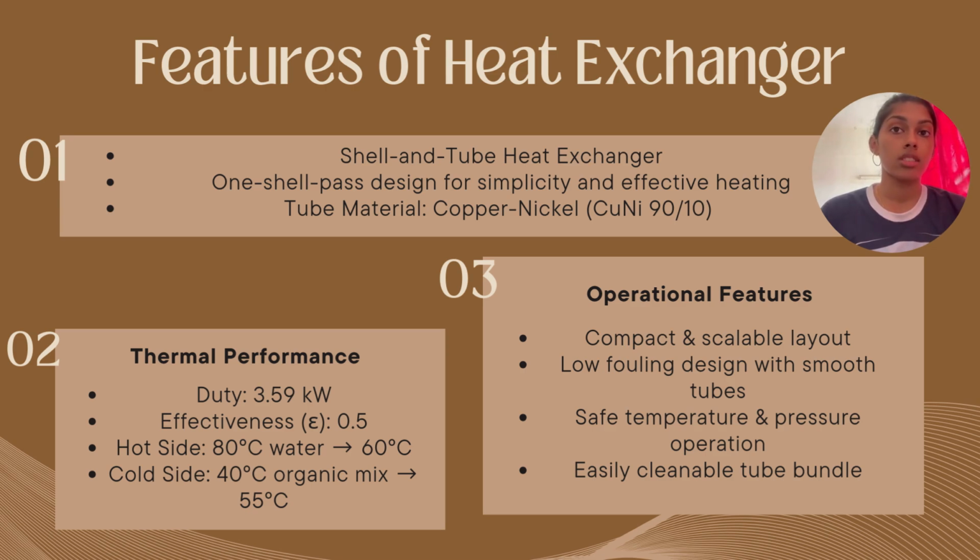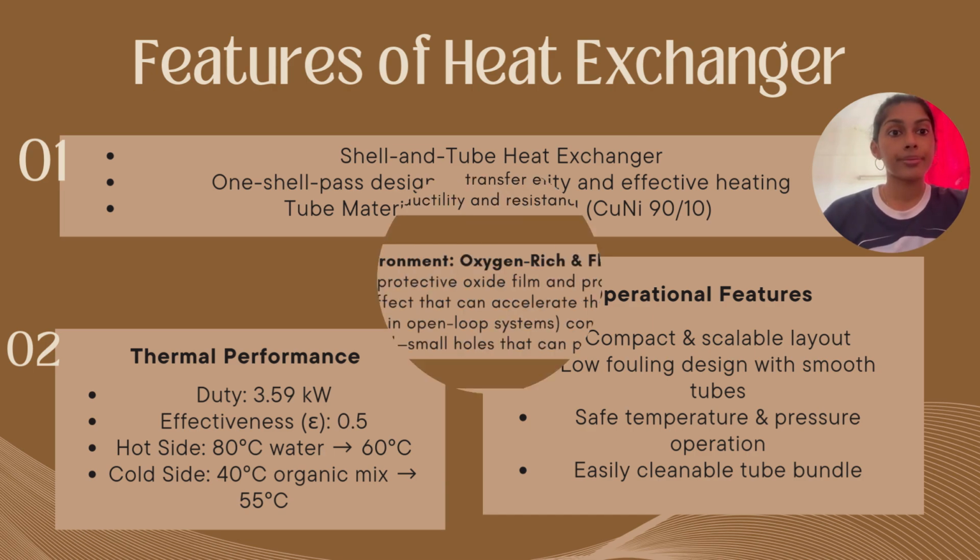The effectiveness is 0.5. The hot side is the water from 80 degrees Celsius, which cools down to 60 degrees Celsius, and the cold side is the organic compound, which is the mixed compound, at 40 degrees Celsius and heats up to 55 degrees Celsius. For the operational features, it includes compact and scalable layout, low fouling design with smooth tubes, safe temperature and pressure operation, easily cleanable tube bundle.